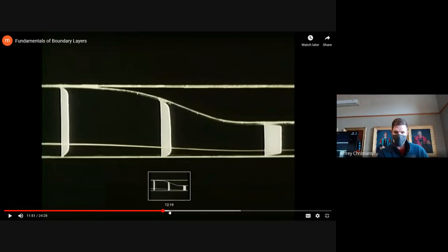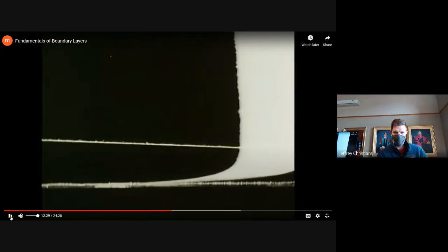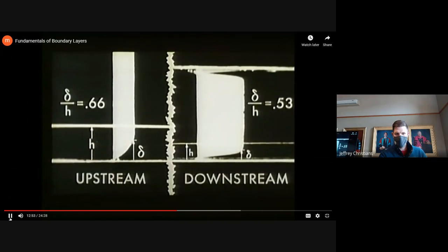Okay, so he'll talk for a little bit about stuff that we're kind of glossing over. So we'll jump ahead, but you can think, when you're going through a contraction, the boundary layer would be generated with the pressure pushing in the same direction that the fluid is going and keeping things moving along. The combined flow at the end is relatively fast because you have a free flow as well as the boundary layer.